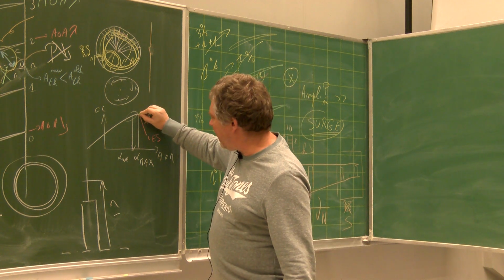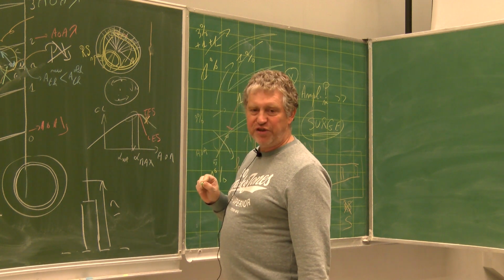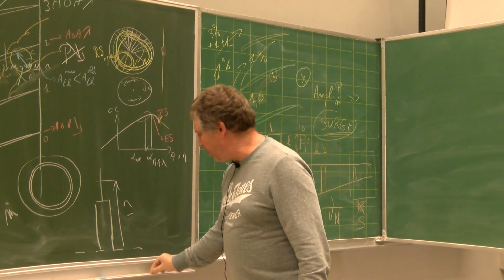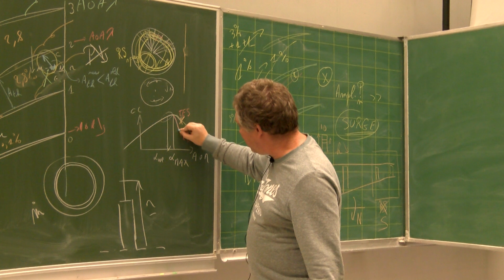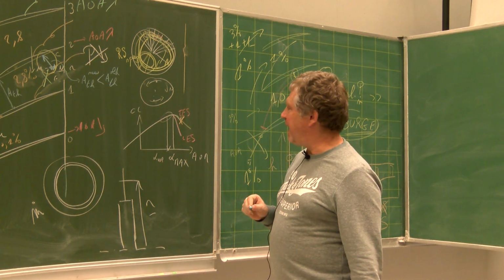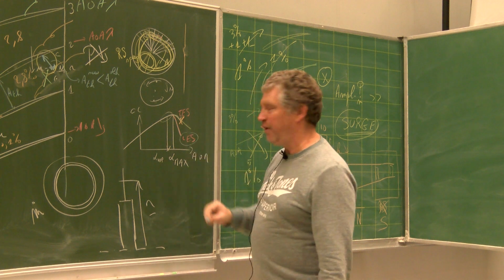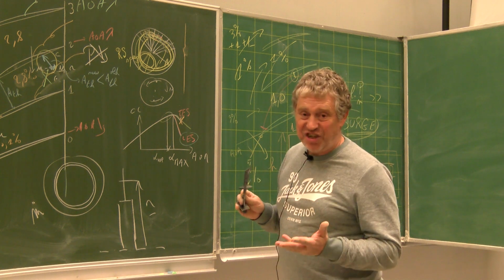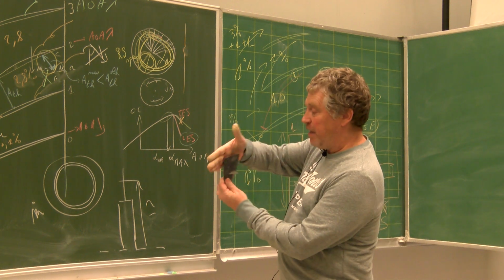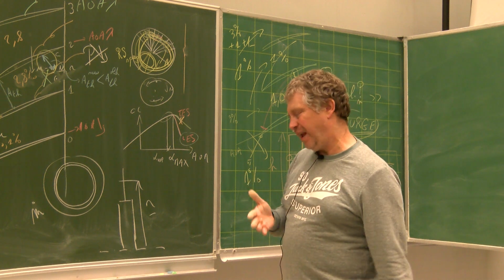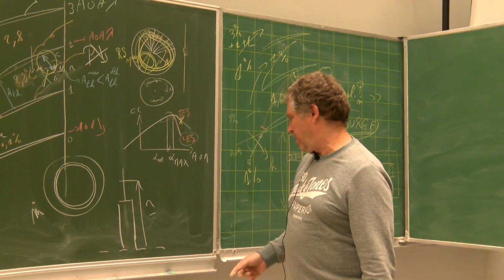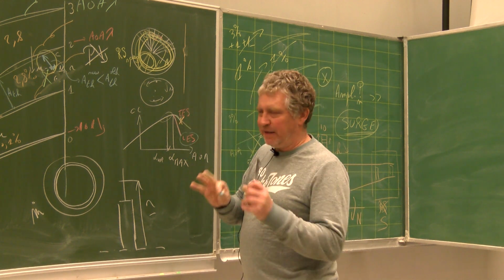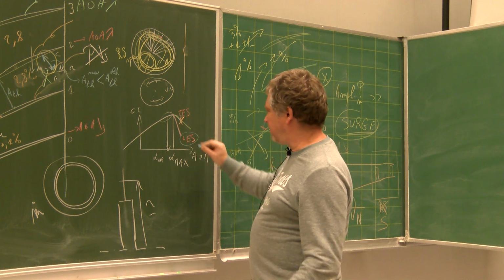Depending on the shape, you will have an airfoil with such a curve, because it will have a trailing edge separation, or you will have another airfoil with this shape of CL as a function of the angle of attack, because this airfoil is flatter and will separate directly over the full length, or the full chord, of the blade.